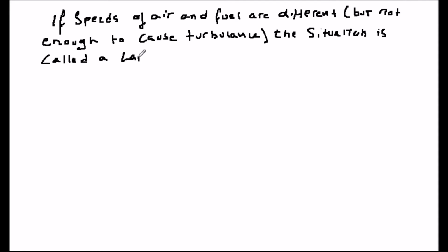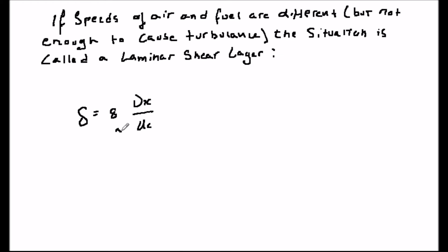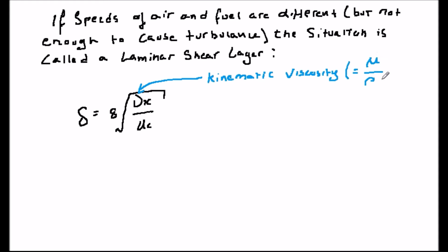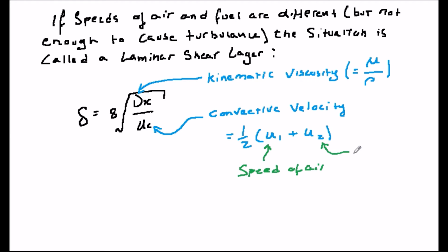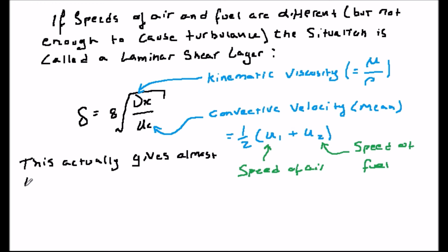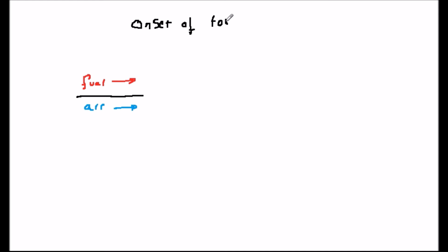The approach outlined above assumes that the air and fuel are moving along at exactly the same speed. In the analysis presented in the book Hypersonic Airbreathing Propulsion, it's shown that the result when they're moving at slightly different speeds, not fast enough to cause turbulence, is very similar. When the difference between the flow velocities of the air and the fuel becomes large enough, the flow becomes turbulent.